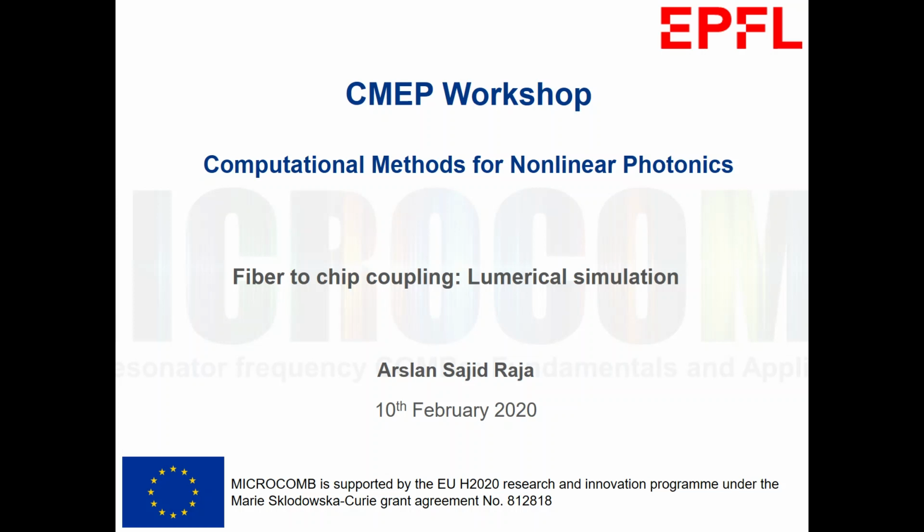So how we can really optimize our design to decide what is the gap distance between our bus waveguide and the resonator. But I will mostly talk about how we can couple the light from an external source using optical fiber to our photonic chip. This is very important because the more light we can couple to the chip, the more power efficient our system will be. So our overall efficiency of the system will improve.